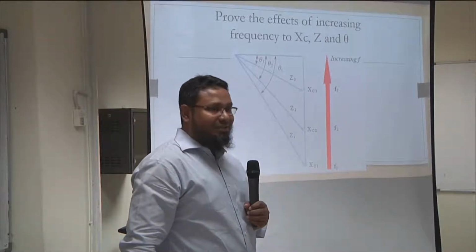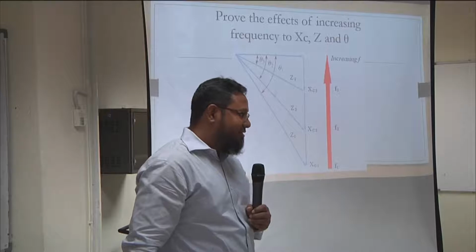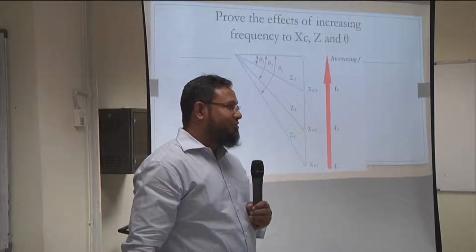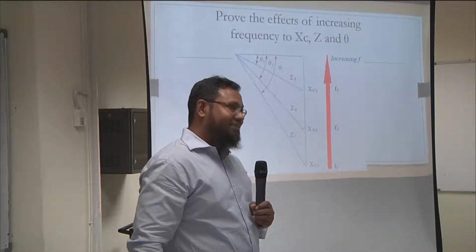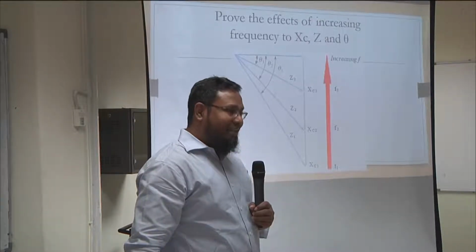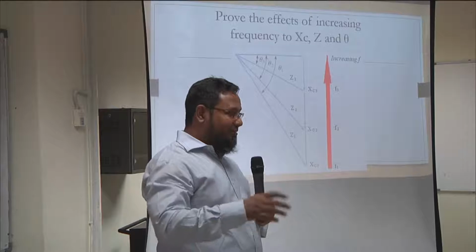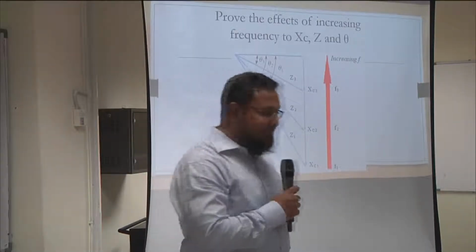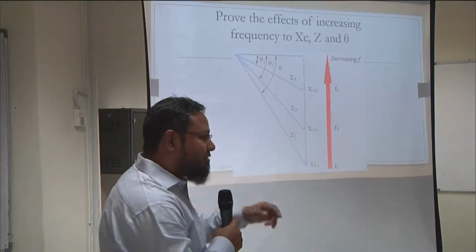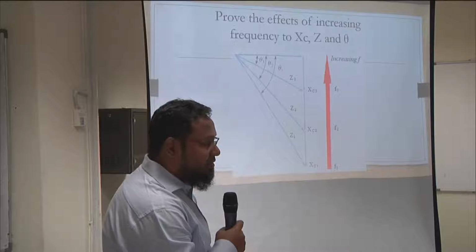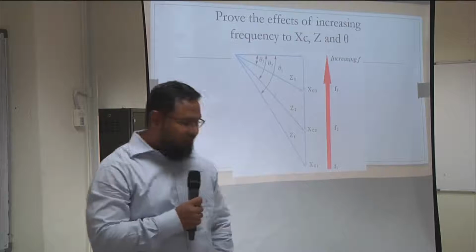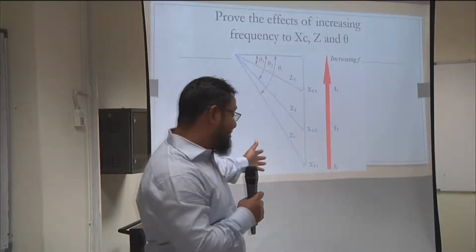So what does that mean? Whenever you have a resistance or impedance 0, that means short circuit. That actually means it's short circuit. So capacitors act as a short circuit in high frequencies. So this is an approximation that is made in many electrical analyses, that in case of very high frequencies, capacitors are considered as a short circuit. So let me ask you this now. What do you think will happen in case of very high frequency? Okay, let me stick to the capacitor.